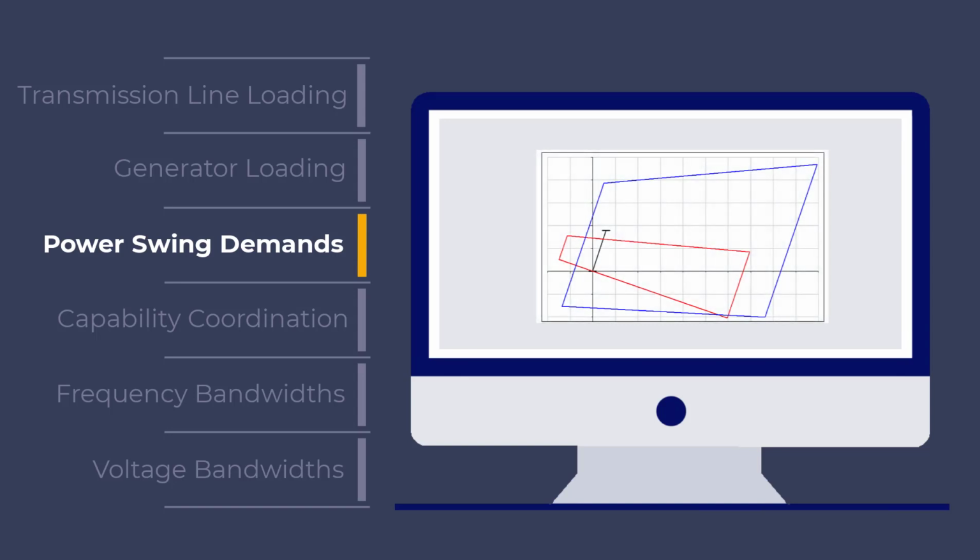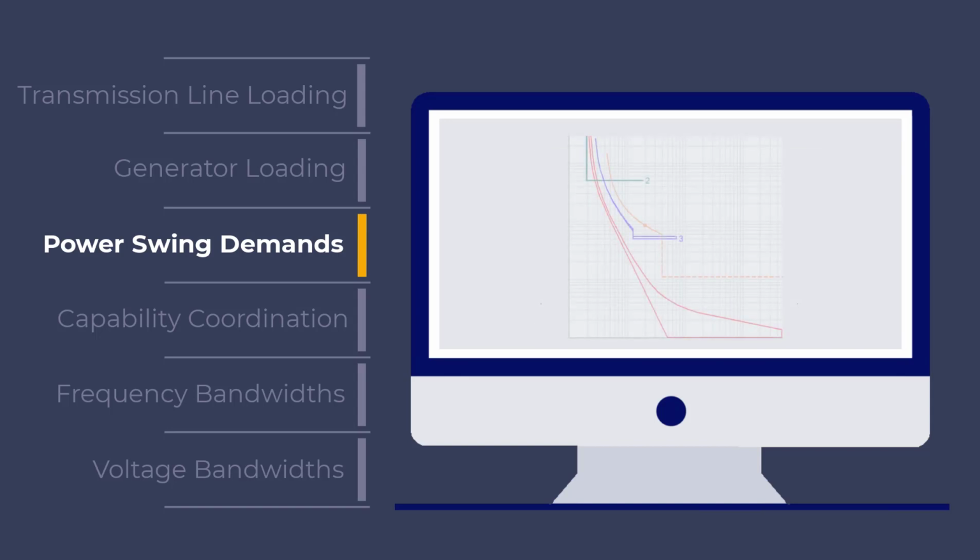The currents and voltages at points on the boundary are supplied to the distance element to determine if it intrudes on the protection characteristic, leading to a potential compromise of its behavior during stable power swings. For the analysis of the performance of phase overcurrent protection elements, the relay's response is determined by comparing the pickup settings with the maximum currents that can be present during the disturbance events.